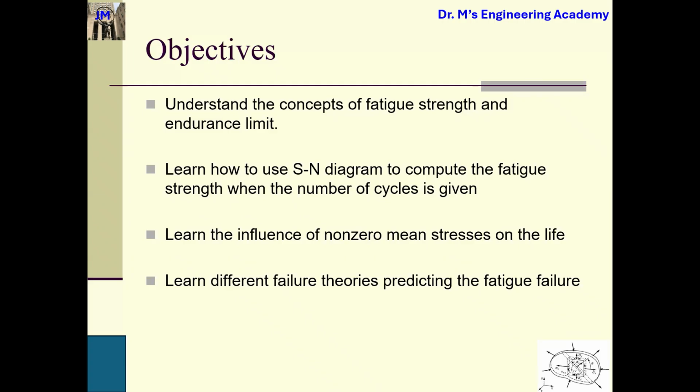So even though the stress level is very, very low, as long as you apply this back and forth cyclic loading, finally it will break. Also, fatigue is very difficult to discern. If you do not pay attention to it, sometimes it happens. But as a responsible mechanical engineer, when we design anything, we need to consider the loading conditions we might have. If the loading condition is cyclic, you need to do the fatigue analysis before you fabricate the material or the structure system.